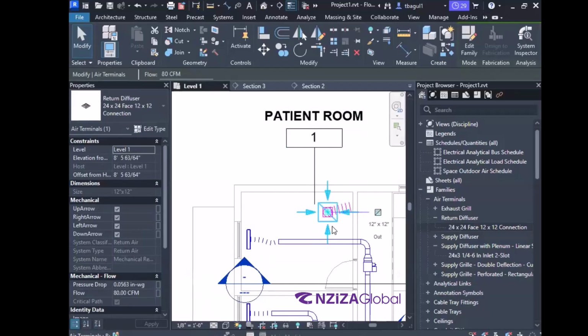That's why we provide a bit more CFM so that the infiltration is countered. So if you are supplying 80 CFM and if we return back, let's say only 70 CFM, supply is more than return, the room is positively pressurized. Does that make sense? Yes.